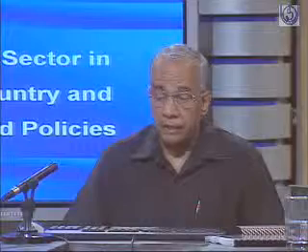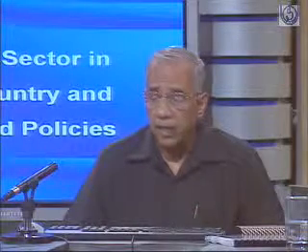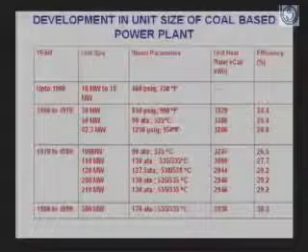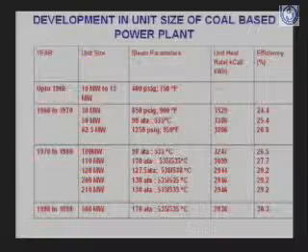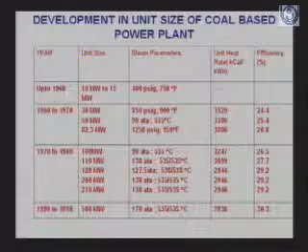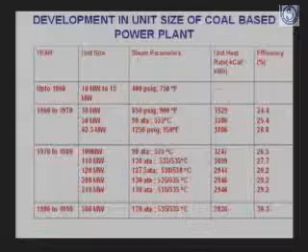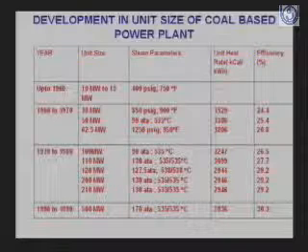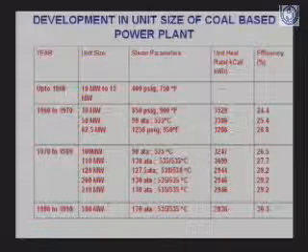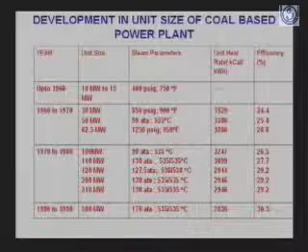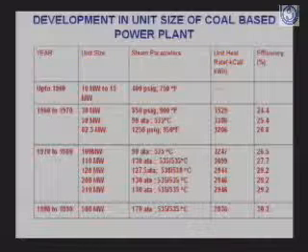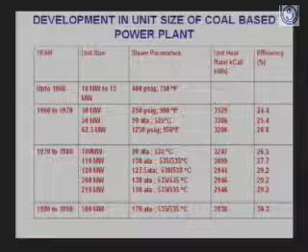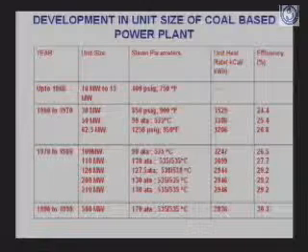per kg, and therefore to give you a broad idea, for generation of 1 unit of electricity, almost 1 kilogram of coal is burned. And this efficiency in terms of percentage is something like 24%, 25%, 26%. That is the level of efficiency. What does it mean? It means that for 1 unit of electricity, if we burn 3500 kilocalories or 1 kg of coal, only 30% of this is converted into electricity. 70% is a waste.